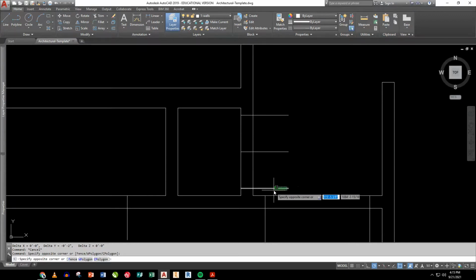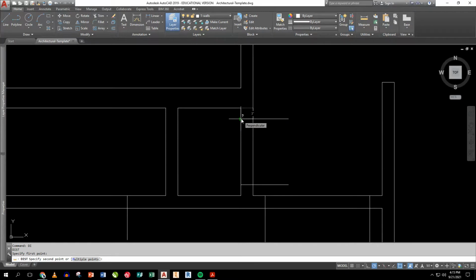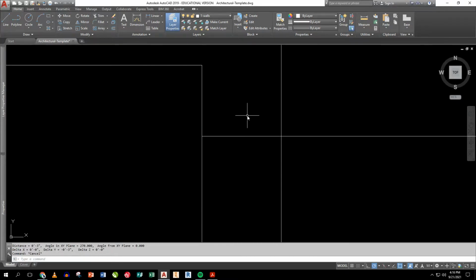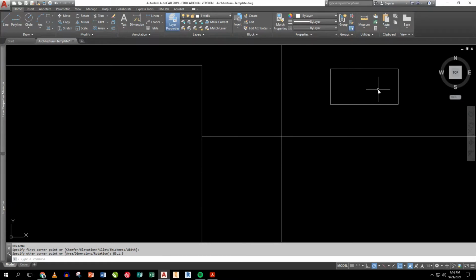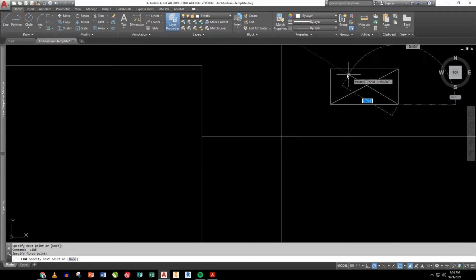So I'm going to actually do this. Offset 9 inches from here up and from here down. Now that should give me a 3-inch area right here. So it's distance from here to here. I just typed in DI, enter, 3 inches. Reason being, I'm going to draw a rectangle that is right here at 3 by 1.5. Okay, that represents a stud.